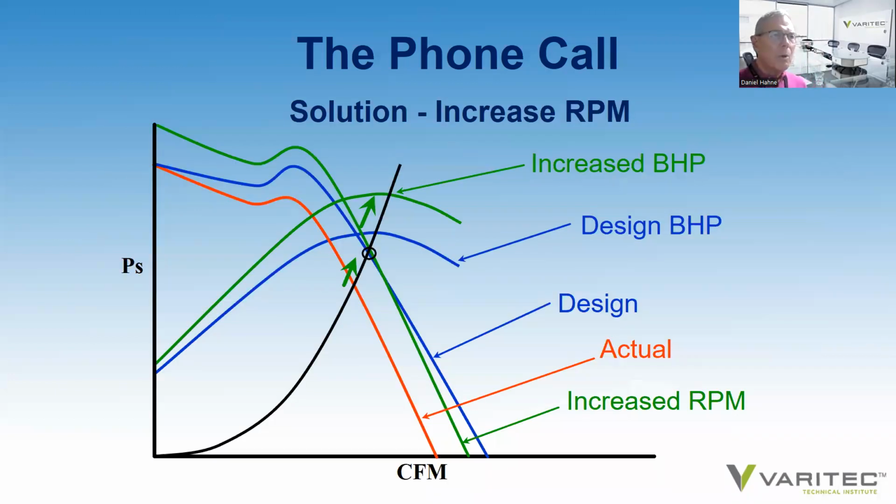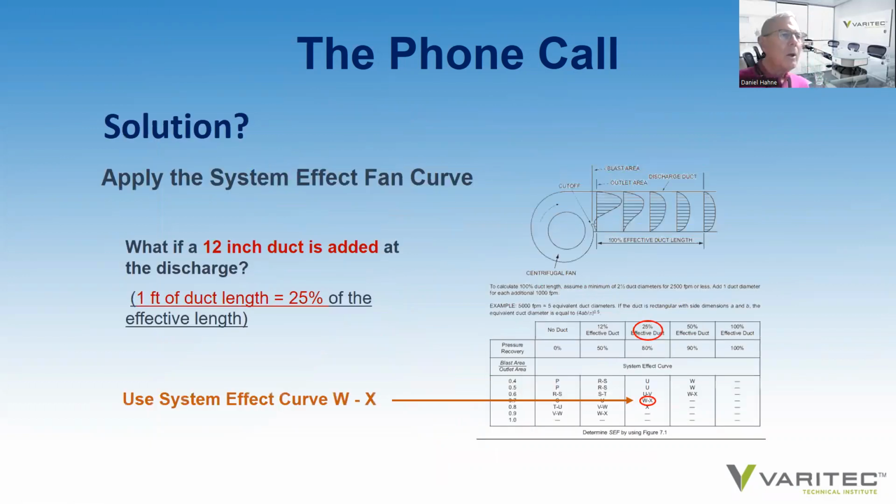So what is the normal result of that? More often than not, in my experience, is, well, we've got to speed the fan up, or we've got to increase the horsepower to overcome this. And in order to do that, we evaluate various fan curves or whatever to overcome the airflow deprivation by the fan. Well, instead of going through all those permutations and the time involved for assessing what that new flow rate might be, let's just sit back and look at AMCA 201 system effect fan charts.